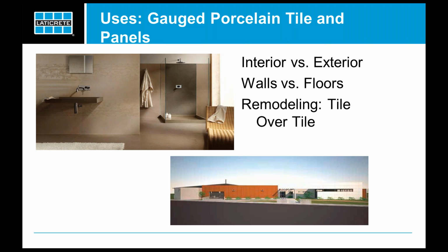Because these materials are so thin and so light in weight, they don't really add an appreciable thickness to an existing floor or wall for that matter, and they're lightweight, so they're not adding really a lot of extra load to an installation. So we're seeing that trend as well with these materials in the tile over tile application. So it's great for remodeling. It minimizes that thicker additional build out, and they're perfect because it keeps the height down and the weight down as well.